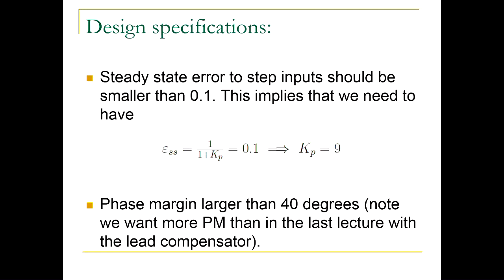Well, because when I shifted down the gain here, the compensator itself would provide some gain. So I would have actually, in the end, something like this, and I picked the compensator gain so that it brings me back to this point. And so the whole idea is to get the desired DC gain, get the desired crossover, right?